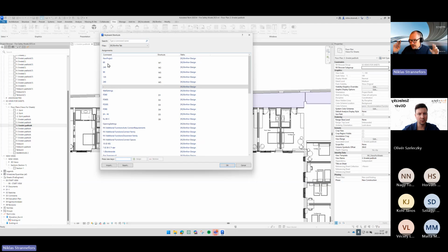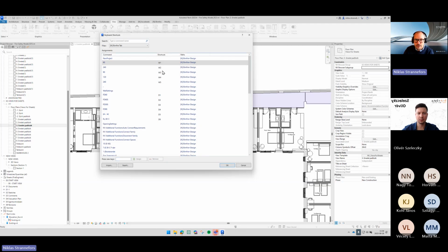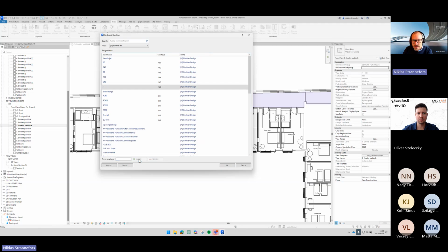These command names are loaded when Revit's open. So if you close Revit and reopen it, what we have selected would appear here. As I know, this is slot 1. I have W1 for wall 1 for that one. You can type whatever you want, so I will type E1, and you can just say assign, and that will appear here as a command. By doing so, I went W1, W2, W3, 4, 5, and W6, assign.